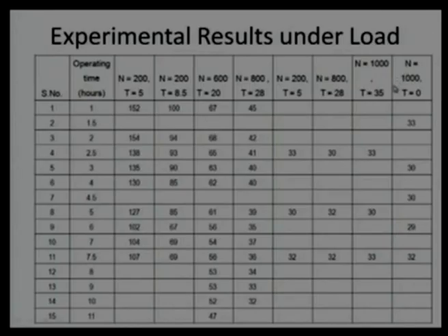Now, here we have removed the load also. We have brought the torque almost to 0 level. Of course, I am not using the word 0.3 Newton meter because all the torques are very high compared to 0.3, 0.4 Newton meter. That is why we put the value as 0. And this is the 0 torque and 1000 rpm. Still, we are getting good results now. That is complete bedding in, completely running in time. We say the running in behavior.